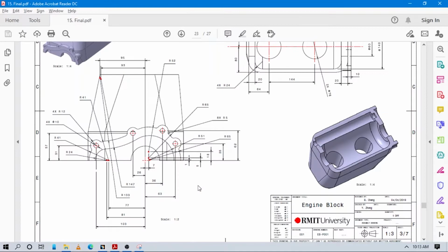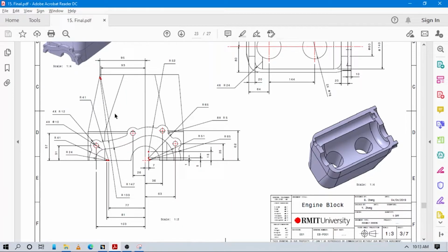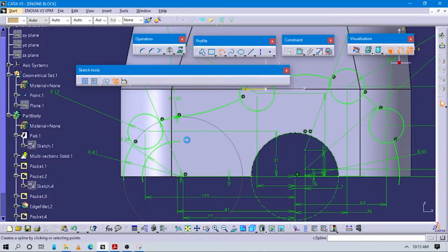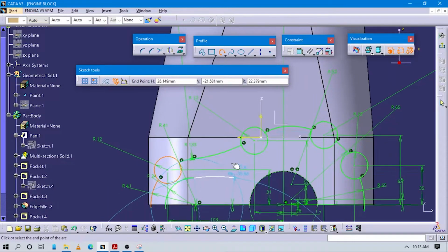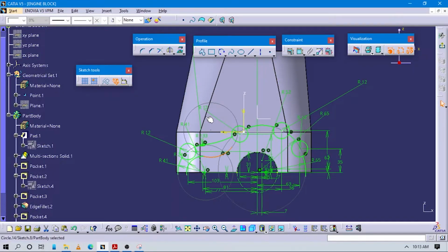And another arc we have to create here, whose circle point is on our upper side and which has radius 147. So create one arc here, somewhat like this. Make sure where the center point comes. You can see the center point is here.